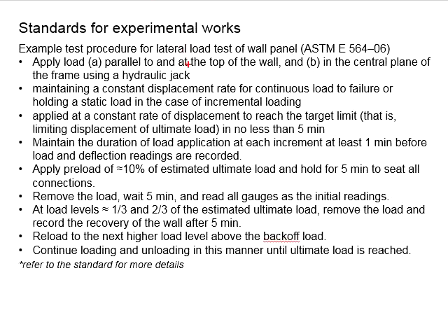One is increasing in terms of the displacement rate. The load can be continuous and the displacement of the wall panel will be quantified, to observe gradual increment in terms of the displacement of the wall until the failure of the wall. Or the second way it is conducted is holding the load as a static load when you need to increase it stage by stage.